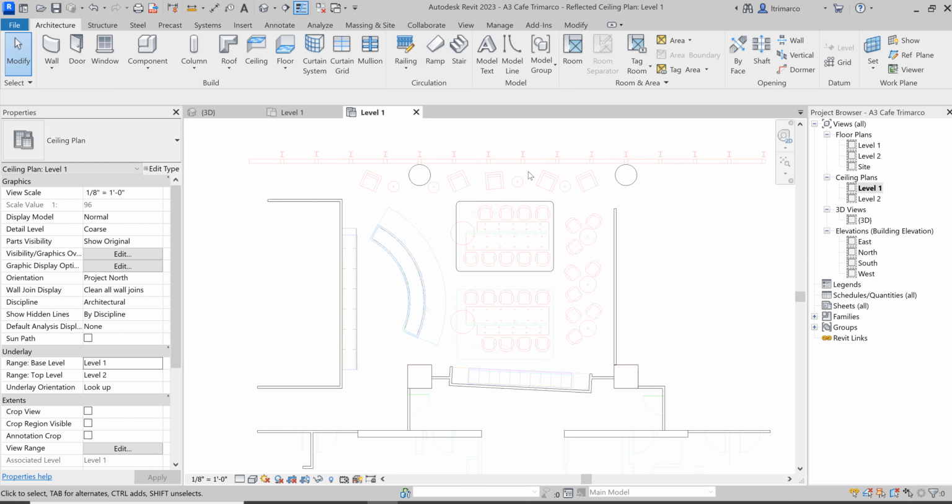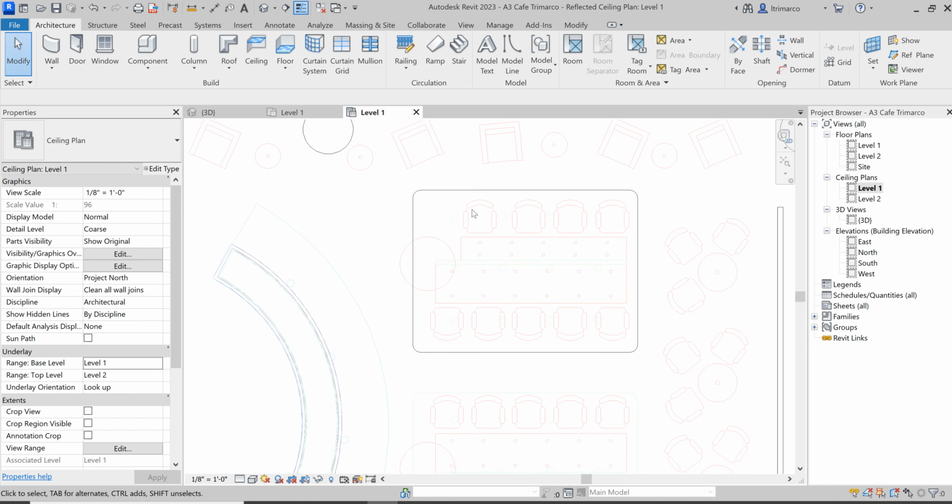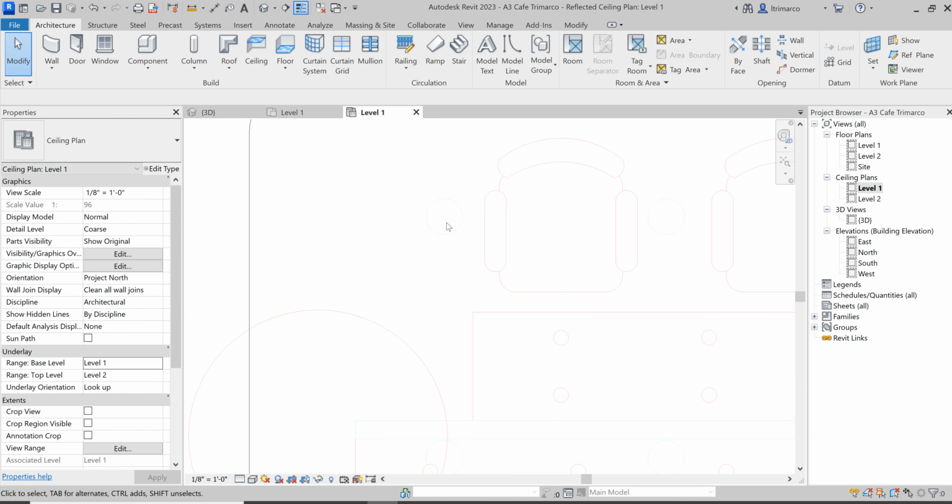You can see it's just a faint CAD drawing, a little difficult to see. The recessed cans, the circles that I drew in AutoCAD, they're on the color green, a little hard to see. So, again, as I zoom in, hopefully you can see that a little bit better. Anyway, let me place one light and then look at it in 3D to double check it, and then copy it if I need to, which I'm hoping I do.